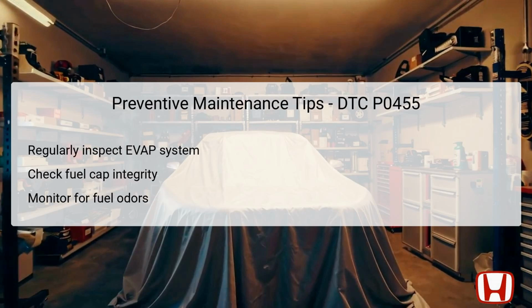To prevent future occurrences of DTC P0455 or similar EVAP system issues, regular maintenance is imperative. Schedule periodic inspections of the EVAP system to check for signs of wear or damage, especially focusing on components such as the canister and purge valve.